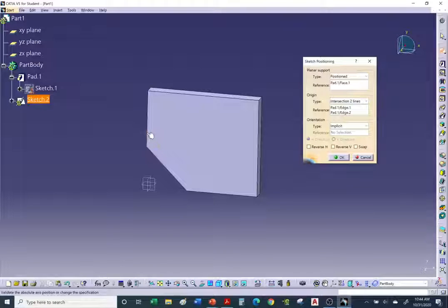So currently you can see the vertical going vertical, the horizontal going horizontally. So now we're going to change the orientation so it lines up with this edge. Okay, so I'm going to go parallel to line, in this case an edge. I'm going to pick this edge, and you'll see our axis rotate. 3, 2, 1, select the edge, and there it is, our vertical. Now it's going off at an angle, so is the horizontal. And the vertical is now perpendicular to the edge, and the horizontal is now parallel to the edge.